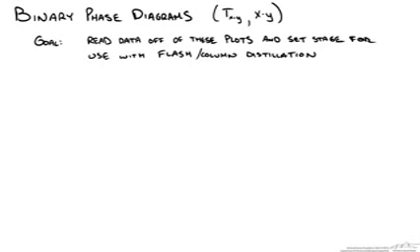We're going to run through reading binary vapor-liquid equilibrium phase diagrams so that we could use them in binary flash and column-based distillation calculations, like those done using the McCabe-Thiele method. So the first place to start is either using a thermodynamic model to predict equilibrium behavior, such as the modified Raoult's law, or the Peng-Robinson equation of state, or the UNIFAC method, etc. Or you're going to look up experimental data collected and published in handbooks, such as Perry's Chemical Engineering Handbook or in scholarly articles. So we want to collect phase equilibrium data.